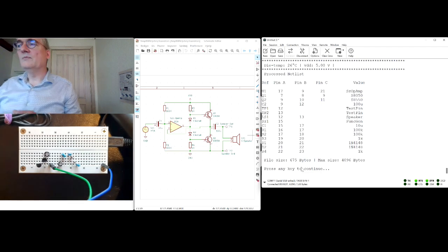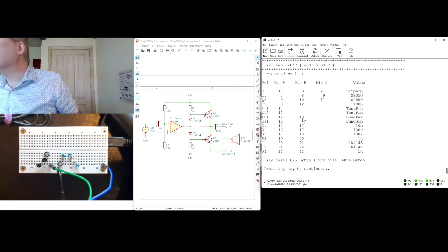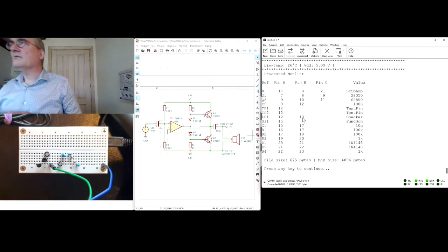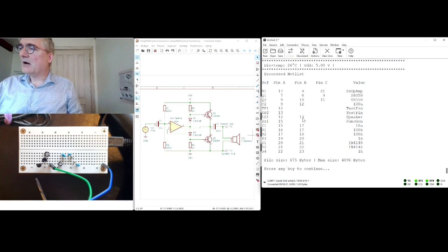Putting it into this, where it did suggest that I should put the loudspeaker into number 13, and 13 is right here. And yes, 13 will be ground, because every pin will either be able to be ground or VDD or something else like a signal, digital signal or analog signal routing. That's also why we do not have any power rails on the side on the Sandwizz Breadboard, because every pin can act like that.